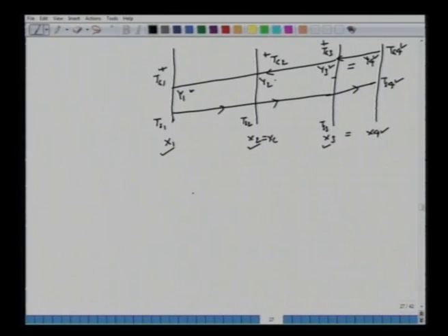All right. So what is the approach? The first thing is that before we make any calculations for theta, we should try to make an overall enthalpy balance and overall moisture content balance, or balances over certain segments, so that we evaluate as many of the quantities not given to us as possible.